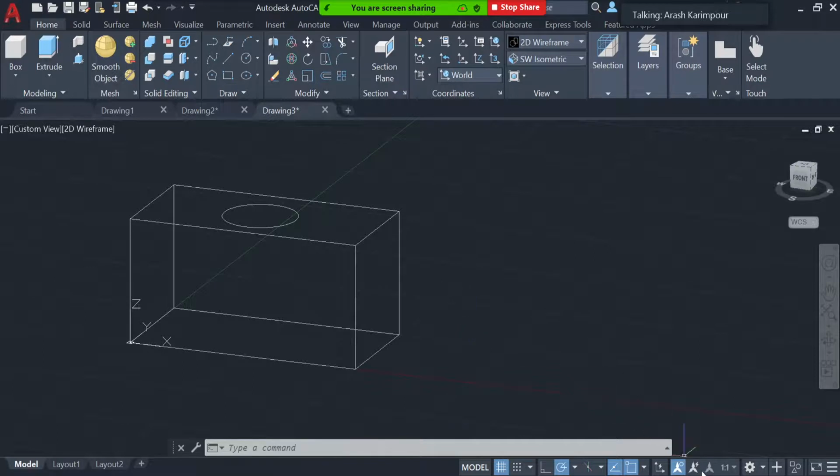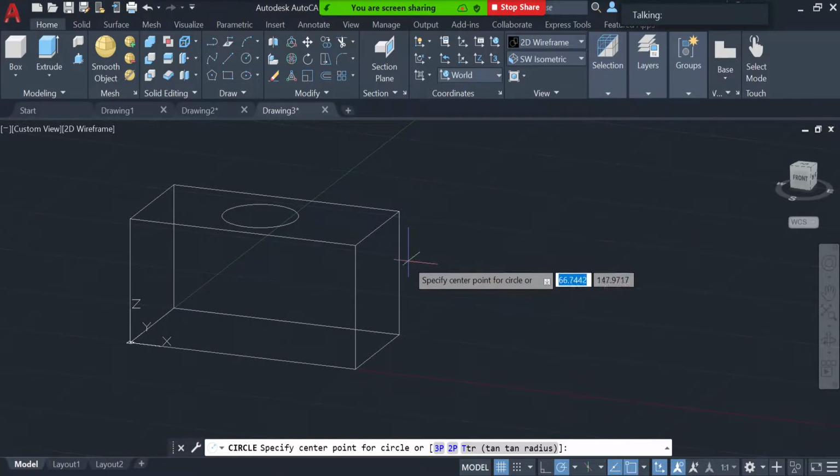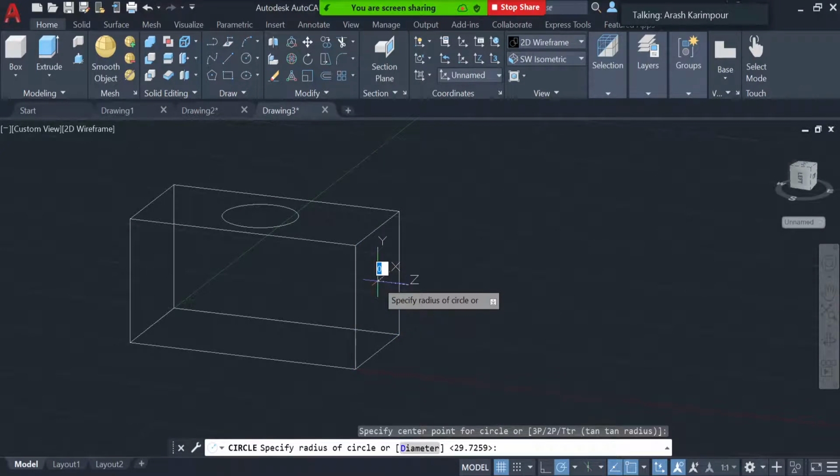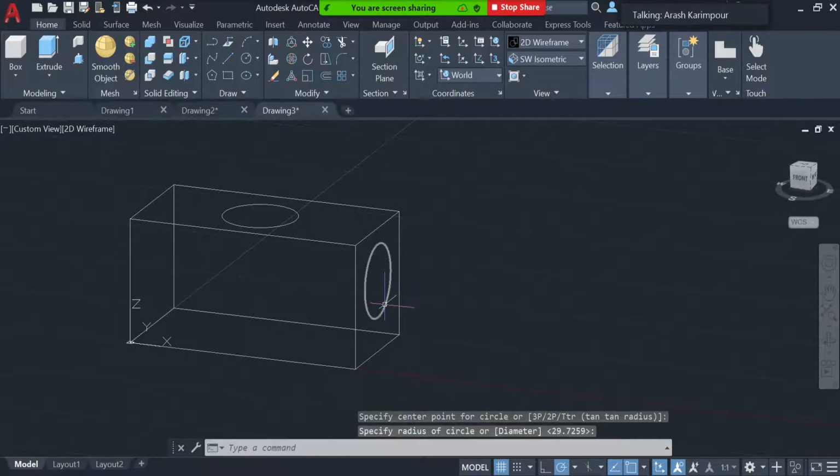And then draw it. Or if I turn on that dynamic UCS, now see what happened as I click on the circle again. As soon as I bring my mouse on that surface, it turns blue, and as soon as I click, you see the coordinate system temporarily comes there. Now I can draw whatever I want there, and as soon as I finish, my coordinate system goes back to where it was. So it depends on what we are doing.